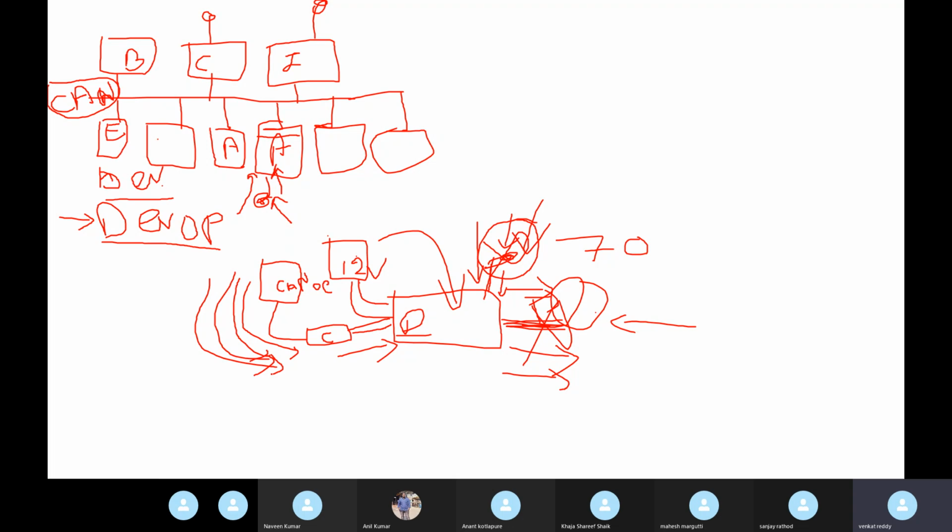Even for vehicle speed, if it is 5 kilometers per hour, it should not be deployed. But so many requirements are there. Though you are at 5 kilometers per hour, another vehicle is at 100 kilometers per hour, and if they crash, it will again take pressure. So this is the requirement. Like that, you have so many scenarios, and we will check different scenarios. Everything, pressure and vehicle speeds, we will send from the CANoe software. Got it, guys? So far.